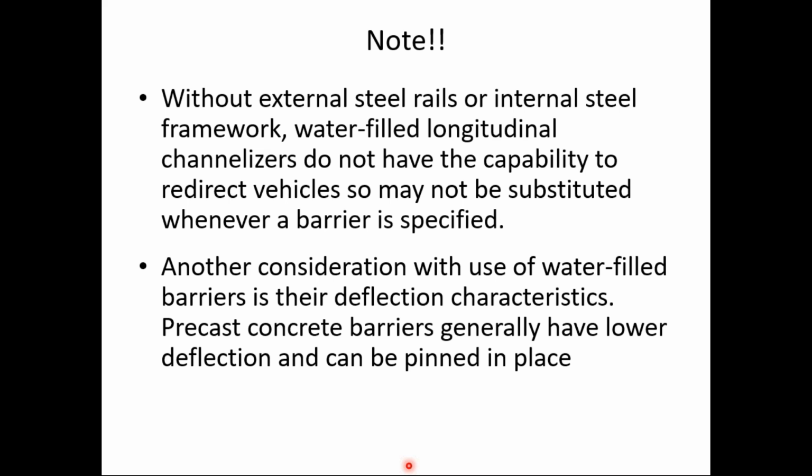Also note that without external steel rails or internal steel framework, the water-filled longitudinal channelizers do not have the capability to redirect vehicles. So you can't just substitute them whenever a barrier is specified. Another thing to think about with the water-filled barriers is their deflection characteristics, meaning their movement when they're struck. Usually precast concrete barriers have lower deflection, lower movement, and you can pin those in place. So you definitely would have positive protection for pedestrians or workers behind those barriers.